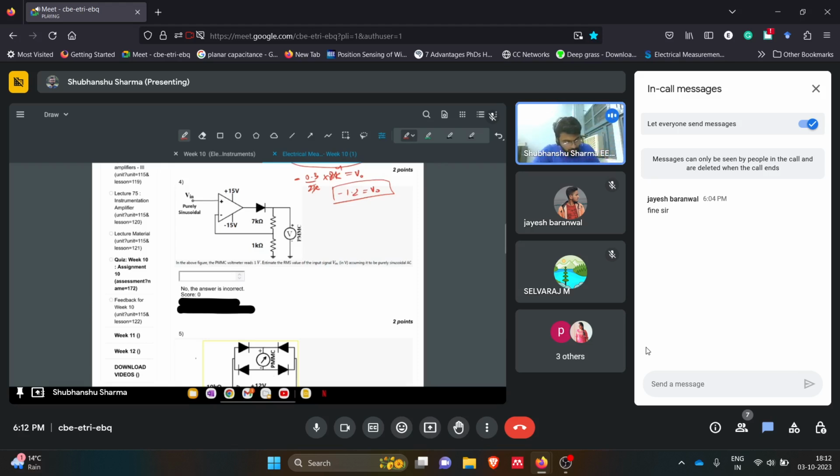I think you know this, but I'm telling it again. If a sinusoidal voltage is input to this diode, we get a half-rectified output, because in the positive cycle of the input sinusoidal wave it acts in its forward bias zone and gives this output. But in the negative zone, the output will be 0, because it acts as an open circuit element.